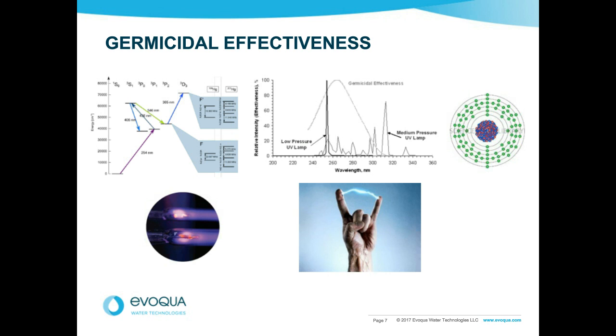A little bit related, does it make sense to use medium pressure lamps for flow streams that have a low conductance value? Well, conductivity isn't so critical to us. What else is in the water, which will impair the passage of light, is more important. If the conductivity isn't very high, it probably means there are other things in the water, like solids and particles. The distribution of particle size is very important. Color is very important. Aside from needing to know the flow rate, the UV transmittance is a critical measurement to take. So I would focus more on transmittance than conductivity.